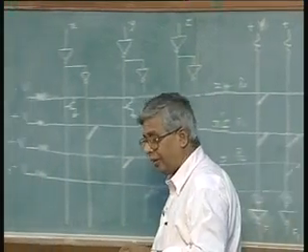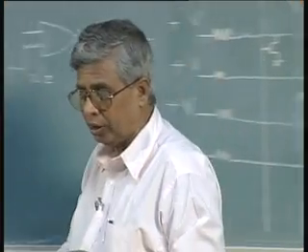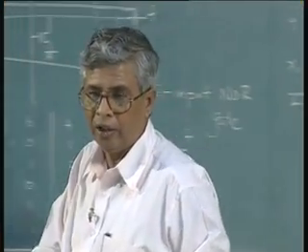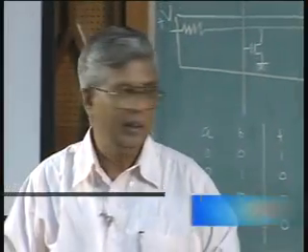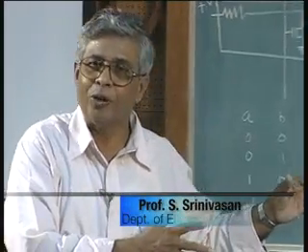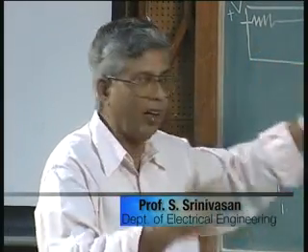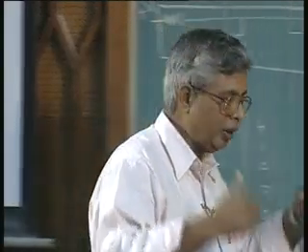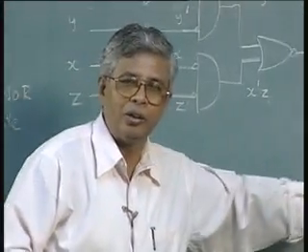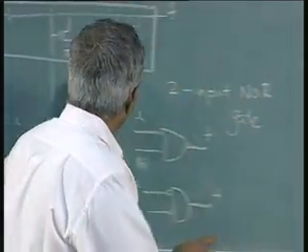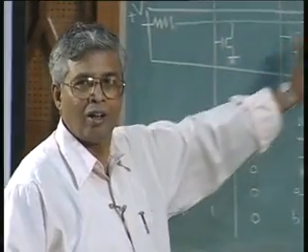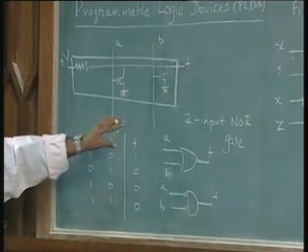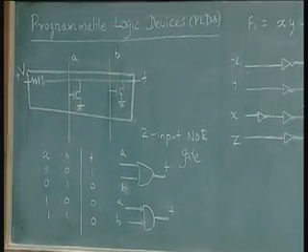This is not hardware. As I said, I am not going to talk too much about the implementation technology aspects of programmable logic devices, but this is a circuit technique we are using, because I am given a function of AND OR inverter and asked to implement it using NOR gates. I need to have this type of circuit technique. So the circuit technique of converting the AND OR inverter into a NOR logic family is what I wanted to explain to you. This is the design using a programmable logic array.